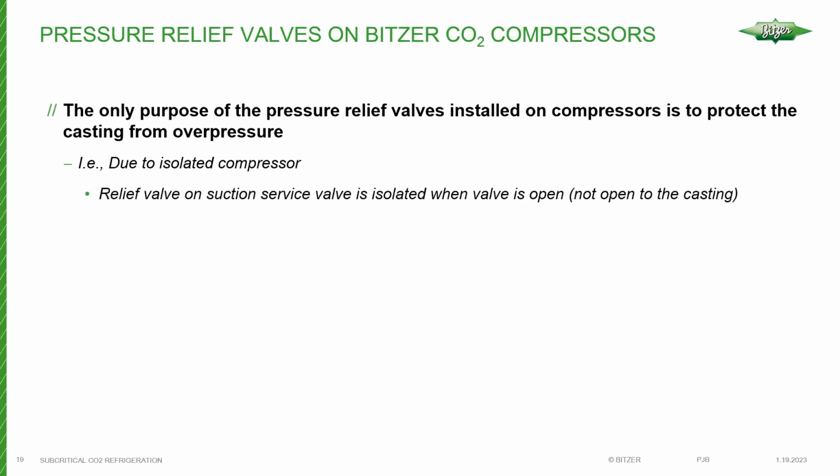For the relief valve that's on the suction of the subcritical compressors, note that the relief valve is only in the circuit when the compressor is isolated. So if there's CO2 trapped in there, the compressor is isolated, temperature rises, pressure rises. If it does exceed the pressure rating of that casting, then that relief valve will open. But note that when the service valve is open, the relief valve is no longer in the circuit.